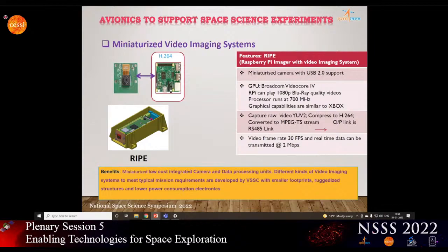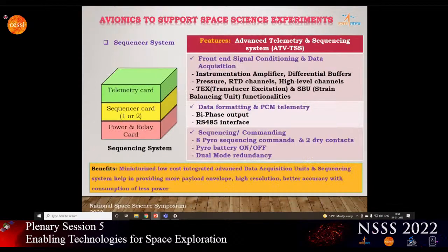So collectively we are using mil-grade as well as COTS-based systems, based on the kind of requirement where the avionic packages are to be placed. Accordingly, we use the component and suitably qualify it through our predefined environmental levels, and other in-house ground level tests. After all such qualification, we fly our avionics system in the sounding rockets.